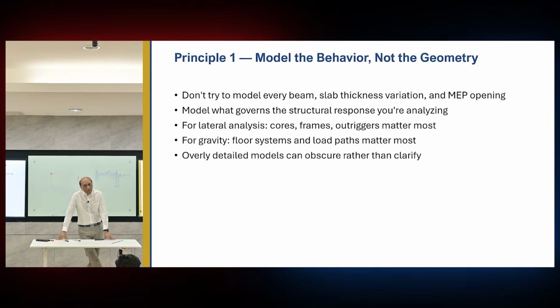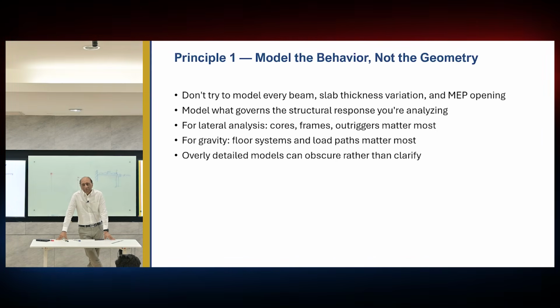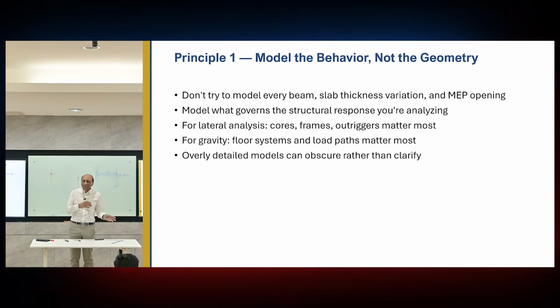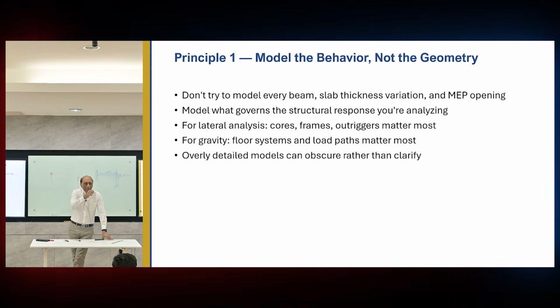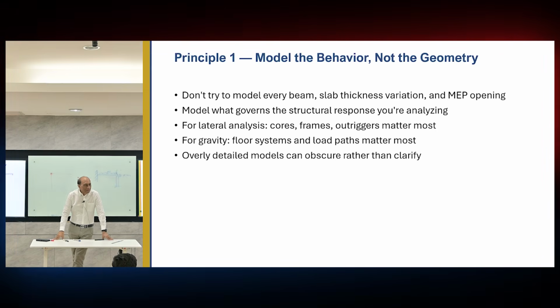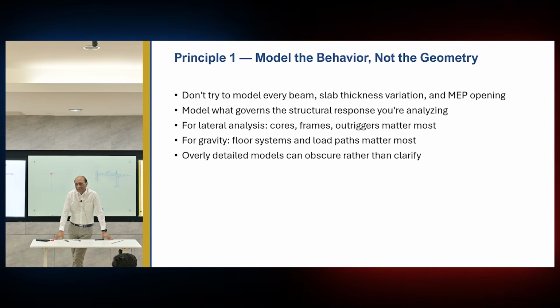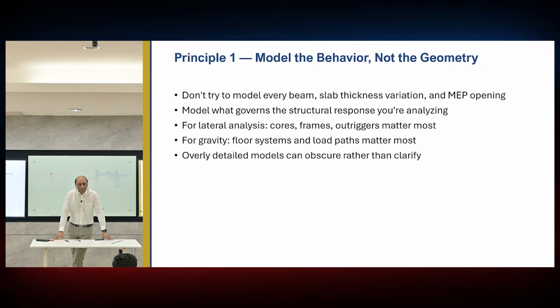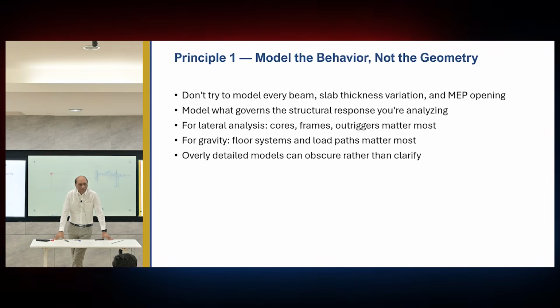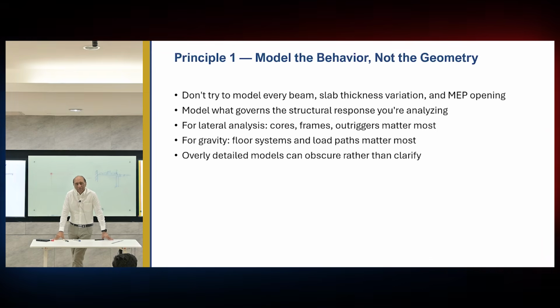But now they have an import function from AutoCAD. So when people import the AutoCAD drawing or model, they bring everything in. Small openings, small pipe things, whatever is in the drawing, they just bring it in. And then they try to create a structural model from that information. So a lot of unnecessary geometry comes in and behavior is missed.